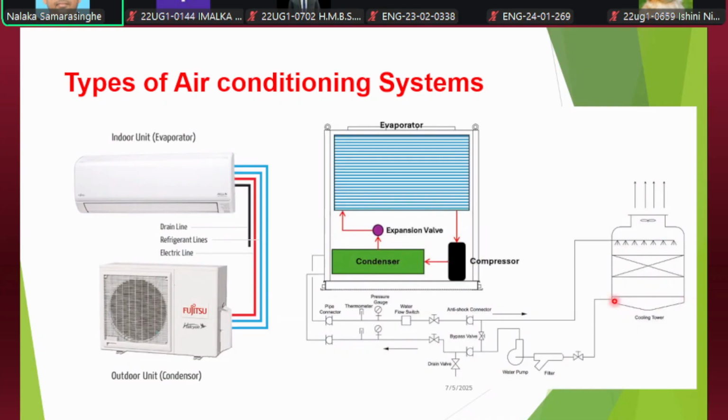After that, the same water will be circulated through the pump into the condenser again. So this is happening in a cyclical manner. The heat rejection is happening here at the cooling tower, so you can use the same water all over again for the cooling of the condenser. As a result, there is heat rejection, and also, in the form of water vapor, there is a drop of the water volume.